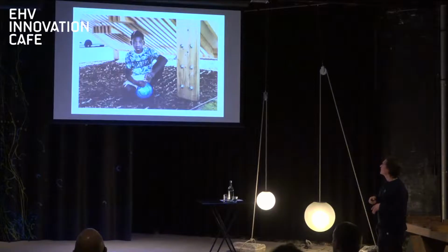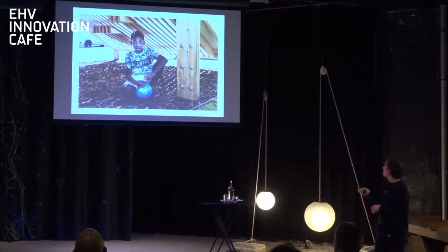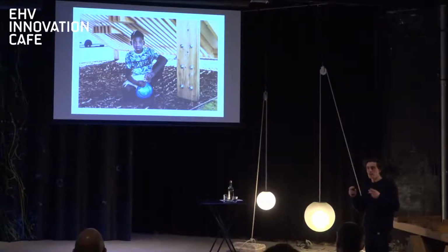Yeah. So this is a last photo of the outside chamber project, where you can see the connection of it's like a steel leg that's on a really simple concrete foundation that forms the base to go up with the timber frame, and by building it with the detail of just butts and not rods and bolts, you can just take it out very easily without damaging the basic construction element.